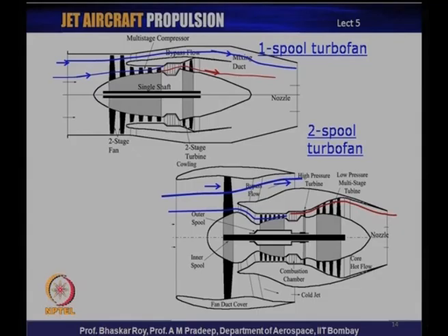In the meantime, a certain amount of flow goes through the compression process, through the combustion chamber, through the turbine, and that hot gas produces power. So, the power is produced only by the inner flow. The outer flow does not participate in the power production, it simply consumes power. The inner flow produces the power through the turbine, and then it goes out and mixes with the cold flow in the mixing zone, and then goes out through the nozzle as a mixed flow, not very hot anymore, but the mass flow of the exhaust is now so much more.